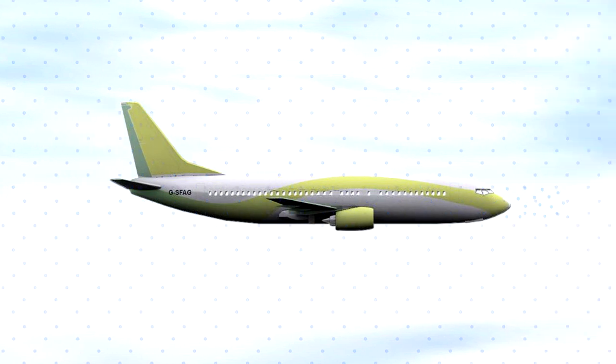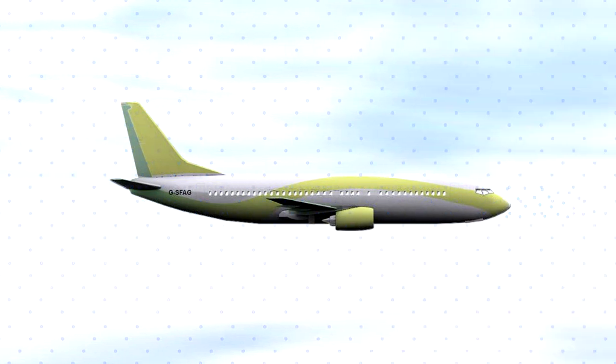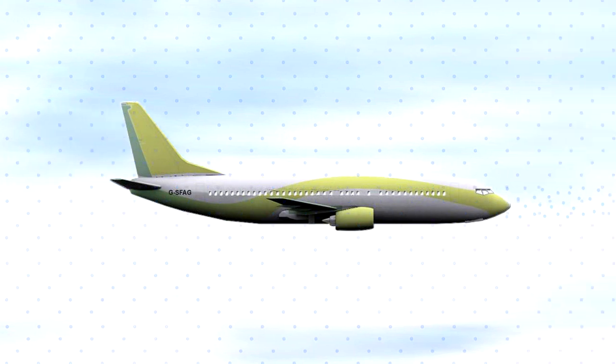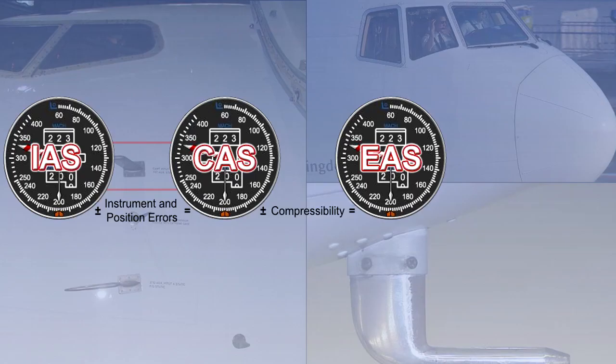As a result, the air starts to build up and compress in front of the airplane. This buildup of air has an effect called the compressibility effect. If the probes are corrected for the compressibility error, as well as position and instrument errors, the speed obtained is called equivalent airspeed, abbreviated to EAS. Equivalent airspeed is the most accurate of the speeds which are obtained from dynamic pressure. For the most part, this performance CD will assume that indicated airspeed, calibrated airspeed, and equivalent airspeed are the same.